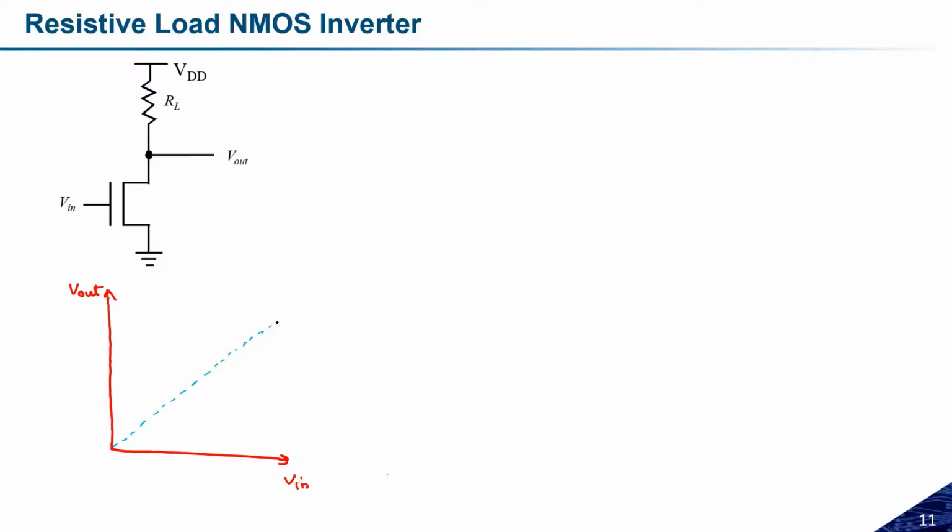These kinds of characteristics are known as the DC characteristics. So you should know these things. How the behavior will be: initially I'm assuming that for the lower input the output should be high, and for higher input it should be something like this. Ideally I'm assuming that the VOL should be as small as possible. But the important thing is that VOL completely depends on the sizing of the transistor, as we explained in the previous slide.